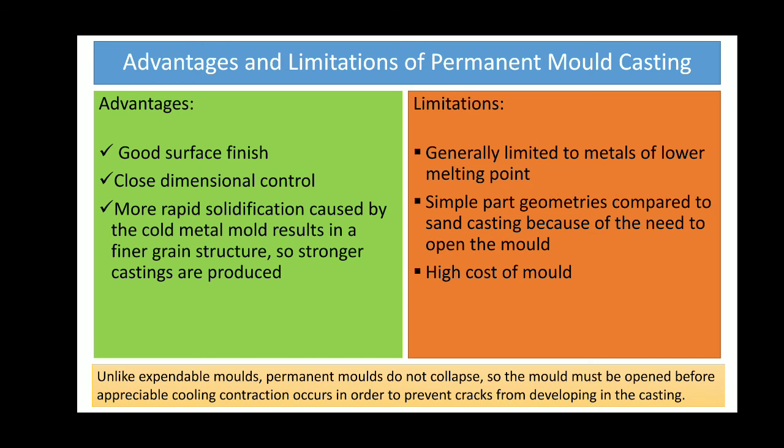Similarly, unlike expandable molds, these permanent molds do not collapse, so the mold must be opened before appreciable cooling contraction occurs in order to prevent cracks from developing in the casting. So this is one of the important things that you must know.